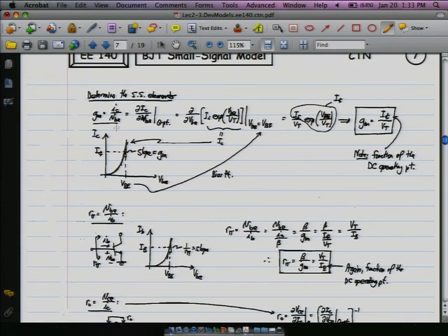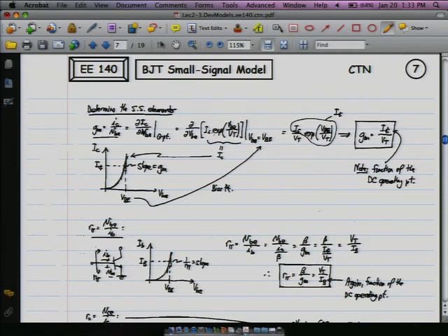So basically where this comes from is it's the slope of this diode curve. It's IC over VBE. And so if we go through this expression and we substitute in our expression for IC, and this is the simplified expression that does not include the fitting parameter, then basically from this exponential we can pull out the VT, and what's left is basically just still the expression for IC, and we get that gm is just the ratio of the collector current to the thermal voltage.